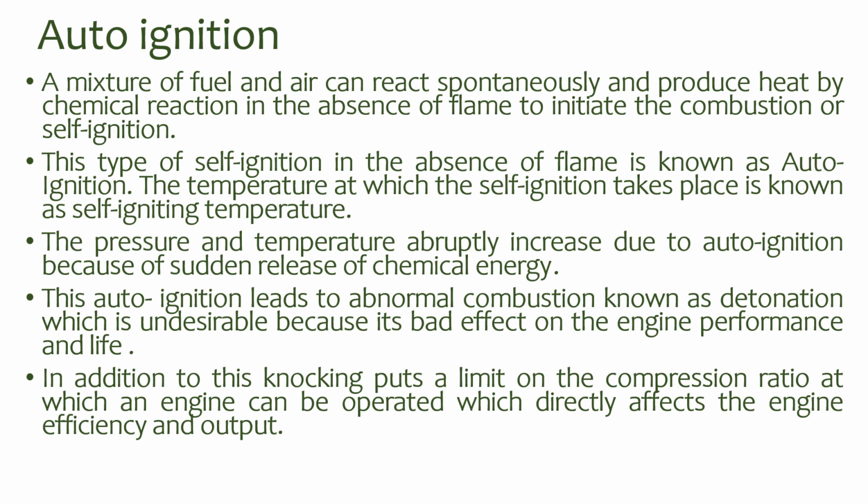Auto ignition. A mixture of fuel and air can react spontaneously and produce heat by chemical reaction in the absence of a flame to initiate the combustion. This type of self-ignition in the absence of a flame is known as auto-ignition. The temperature at which the self-ignition takes place is known as the self-igniting temperature. The pressure and temperature abruptly increase due to auto-ignition because of sudden release of chemical energy.